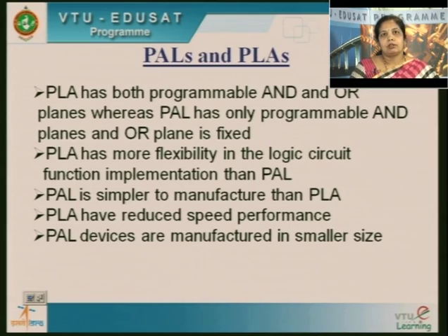So this is what we are comparing, PAL and PLA, both have programmable AND and OR arrays. The only difference is programmable planes and fixed planes. Either the AND and OR both are programmed in PLA, or in PAL the AND gate is programmable and the OR plane is fixed.